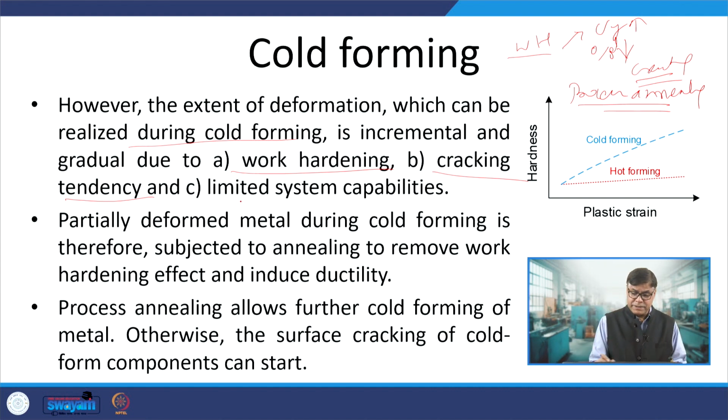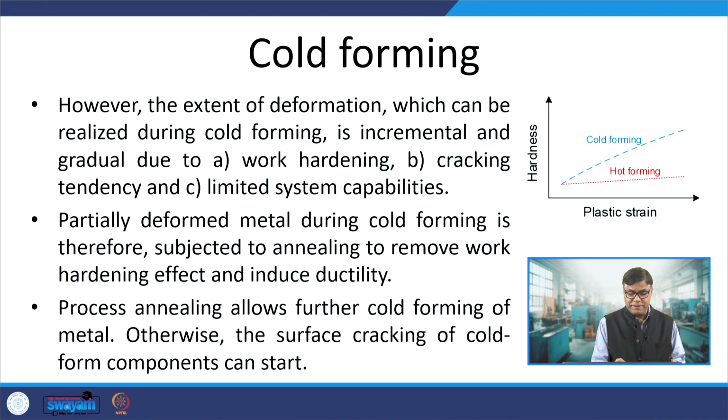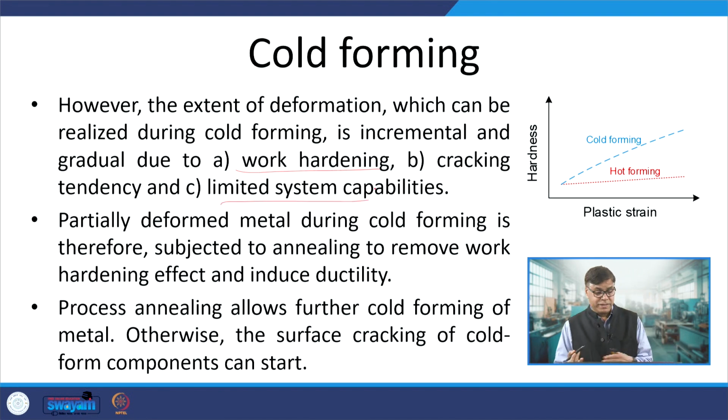And this process is also limited by the system capabilities. If the material has too high a yield strength, it may be very difficult to facilitate the plastic deformation under room temperature conditions, and so it may also be limited by the system capabilities. So these are, you can say, little negative aspects as far as cold forming is concerned. Material subjected to work hardening has increased yield strength and reduced ductility, which makes the deformation difficult, and it requires very high forces to facilitate the plastic deformation. So that's what we can see here.